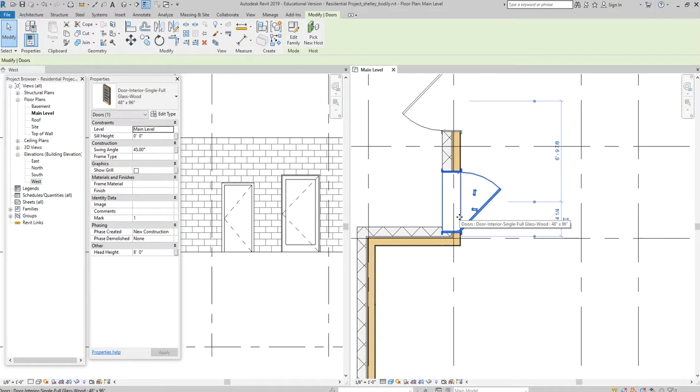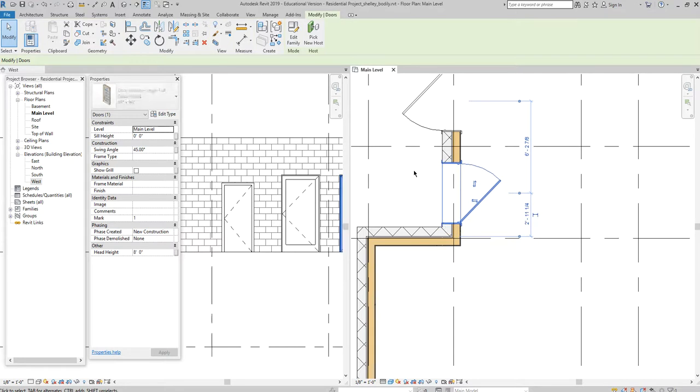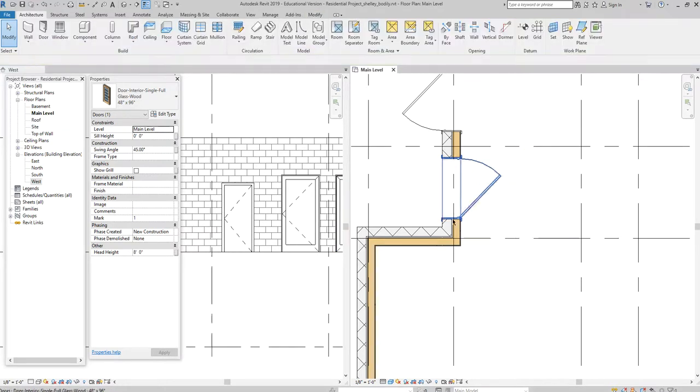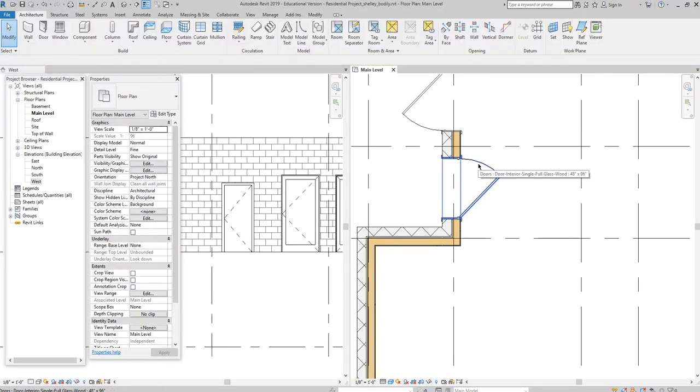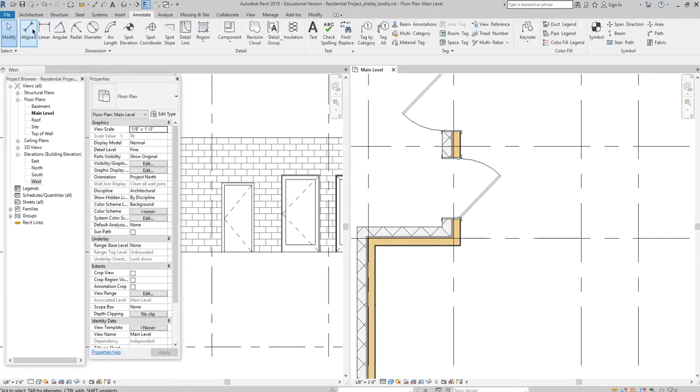It's a lot closer because the door was bigger. So that is one kind of bad thing about Revit. It replaced that component from the center point, and I can't really change that. But I am able to get the door I want. It looks the way I want it to, and I can just reposition it, right? So I'm going to do a dimension, annotate, aligned.